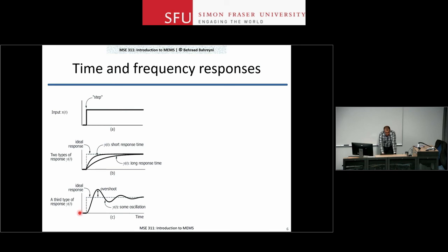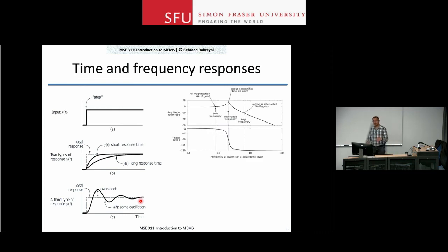The situation for MEMS devices is that you usually get a high Q system and you get ringing at the output of your device, and that is usually your concern. If you look at the frequency response of your device, again, for MEMS devices, you have a high Q, so you see a clear peak in the resonance response or in the spectrum of this device. At low frequencies, where you usually use your device, the response is similar to your static response, and then at very high frequencies, it's like any second order system.